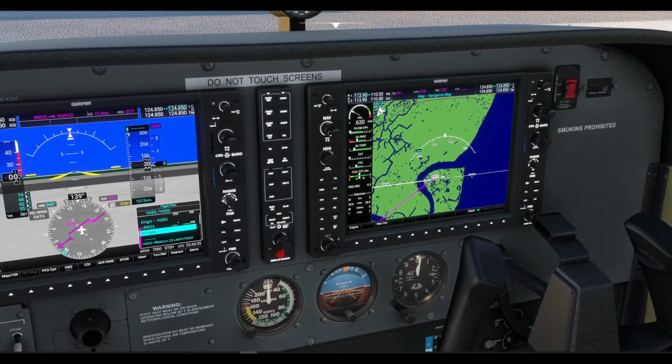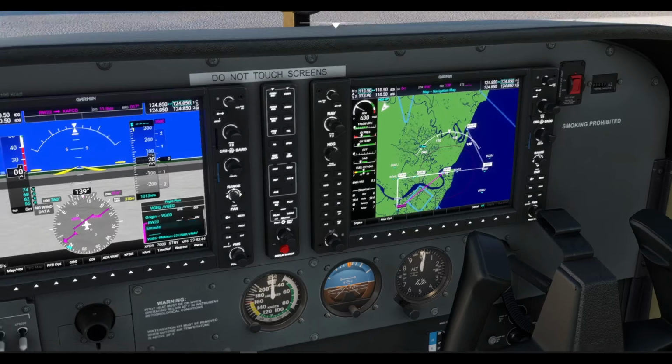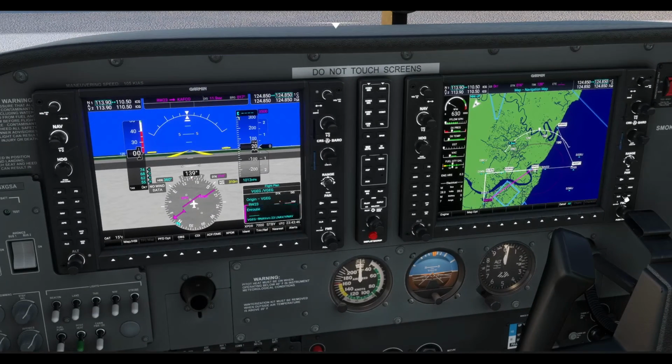So if we increase the range, that's how it works. Kafko, Aldrin, Kanya, and then runway 23. Initially we'll fly on the heading, so we'll vector ourselves toward the Kafko waypoint, while climbing to the altitude of 3,500 feet, and thereafter we'll just follow the GPS. And let me set the altitude to 3,500.